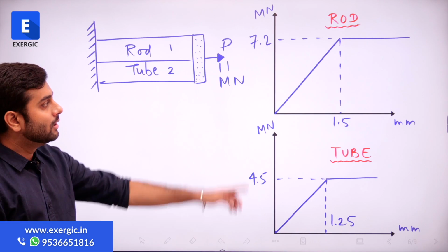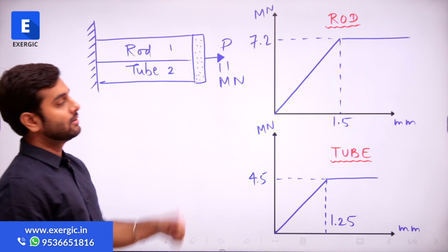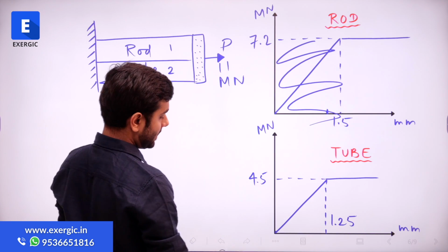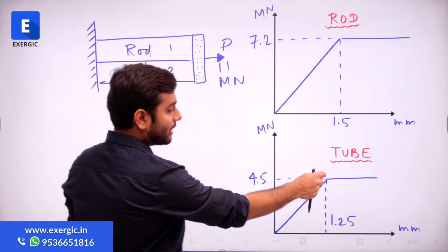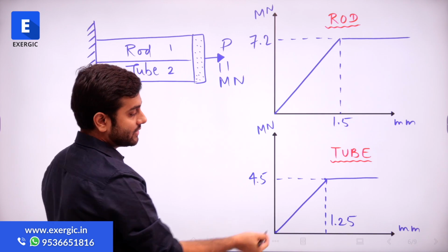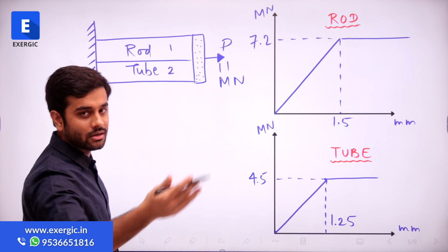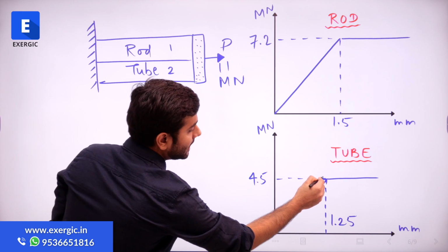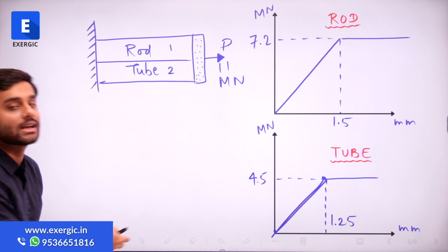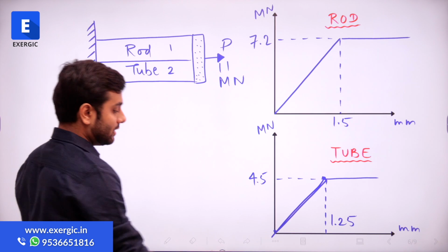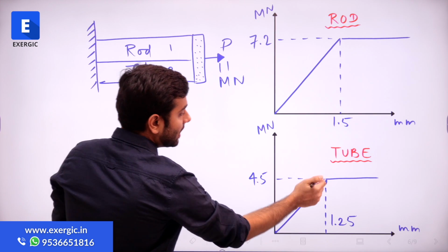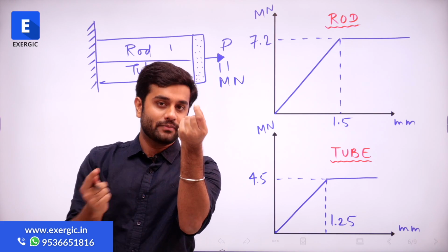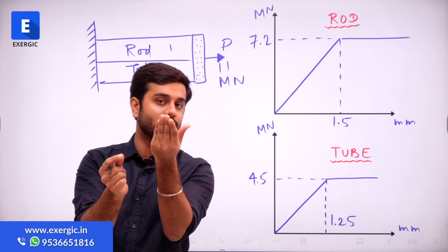At 1.25 mm, this one is definitely in the elastic region, right? 1.25 maybe somewhere here, which is in the elastic region. What about this one? Here it is at the yield point. The equation of the elastic zone which we want to apply is applicable for this line, and this end and this end are both part of that line. So even though it is at the yield point, I can apply the analysis of the elastic part because it is at the border. It is on the same elastic line at one end of it, right or not?